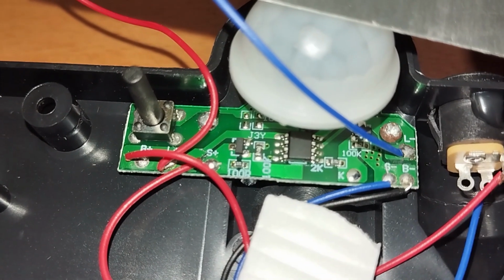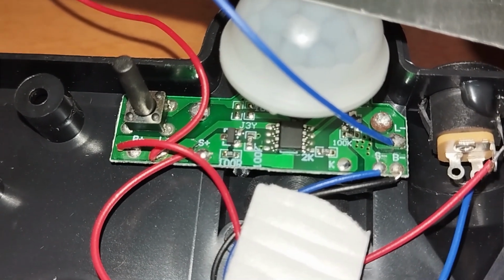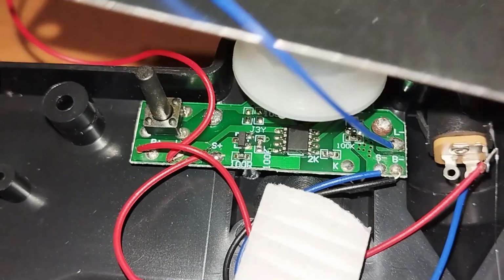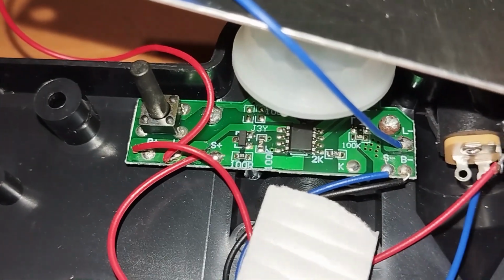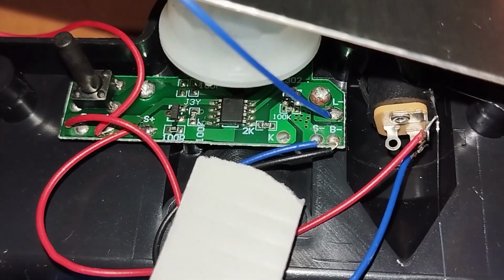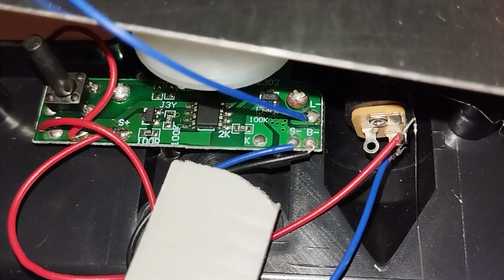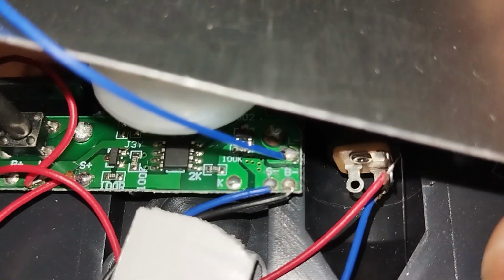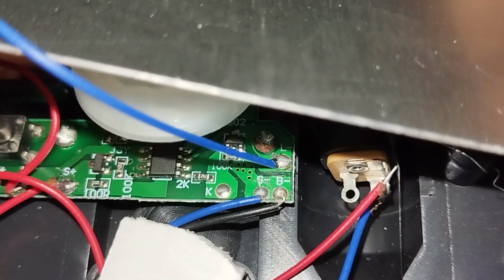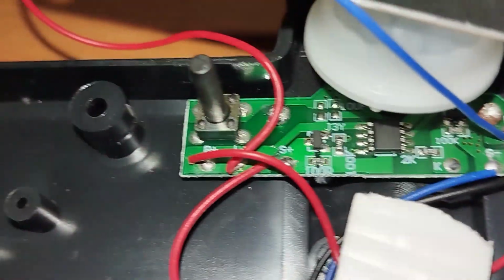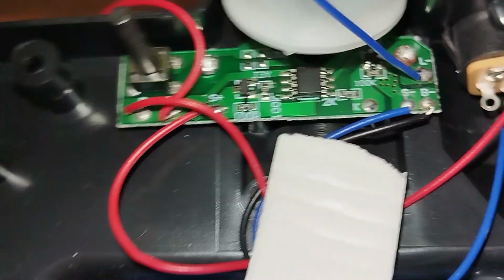I'm going to unscrew the main board. This main board is secured with two screws, but the main thing is that without holding the screw with tweezers it is kind of risky, because if any screw falls onto any contacts, especially the chip contacts, that could be a short circuit. Always remember this is an energized battery. Even if the load is low, you have to strictly take care about any short circuit.